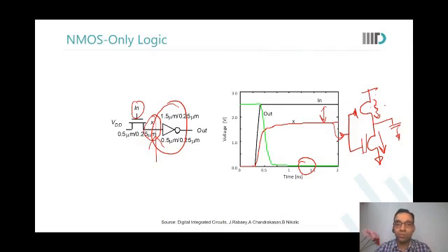So what to do now? I was thinking, instead of implementing our combinational logic using PTL and then using this inverter for the buffer, can't we implement this inverter also in PTL logic itself? If we put this simple NMOS and then connect X to that gate also.